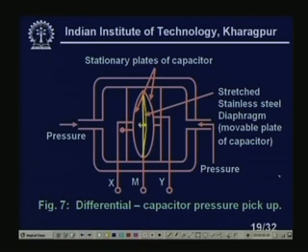Now, this type of pressure transducer, as a differential pressure transducer, has tremendous applications in modern day instrumentation. You will find it everywhere, for example in flow sensors, which as you know are huge in number in the process industry. In all flow measurements, especially in the case of orifice meter, Venturi meter and pitot tube, we use some differential pressure pickup, because this output is to be transmitted to the control room. So, I need this differential tapping. It looks like this in flow measurements.